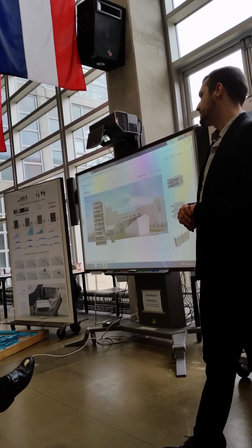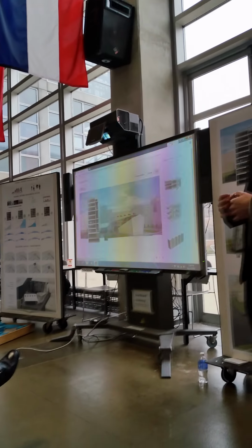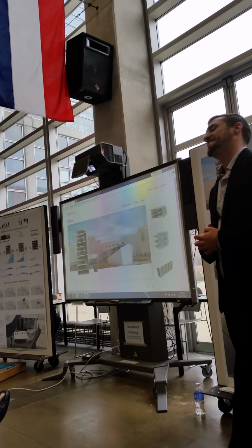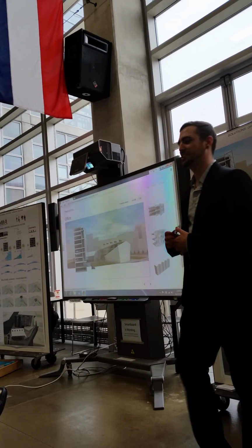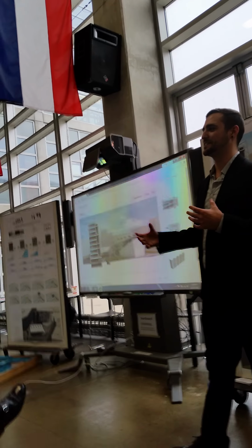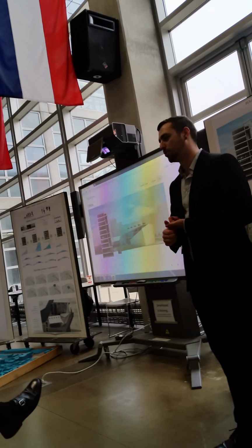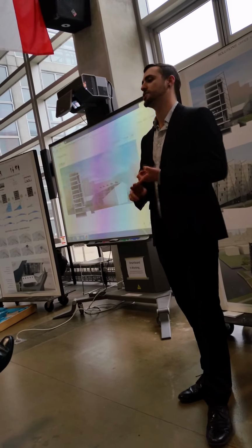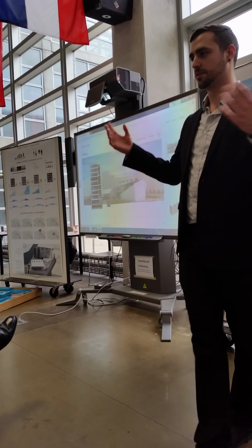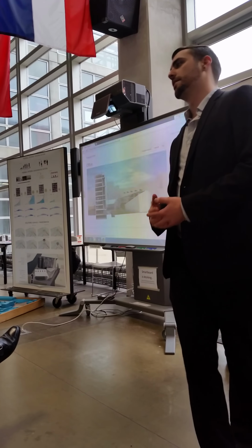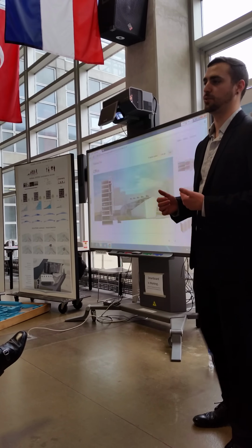And all of these strategies and techniques are based on the fact that we need to engage in how we utilize the building. We can't just turn on a switch and have the whole building heat. People need to play an active role in how they're conditioning or heating the space. So somebody would actually go up and open a window if they were overheating, so that would allow natural ventilation to come in. So the occupant becomes an active participant in the heating and cooling of the building.